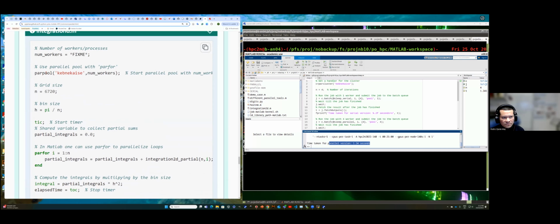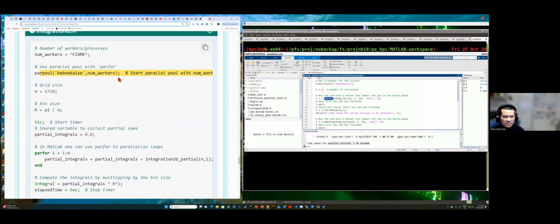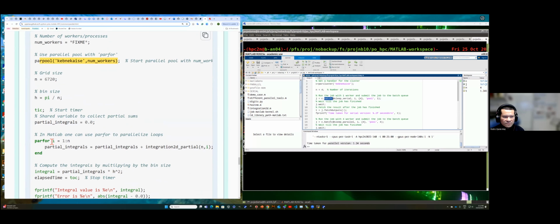Here you will use the parpool. Instead of using the command batch and getting a handler, you just open a pool of some number of workers, and then everything that you execute inside that contains parfor, spmd, parfeval, parsim will be executed on the computing nodes.